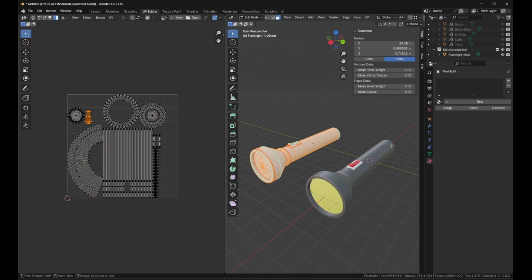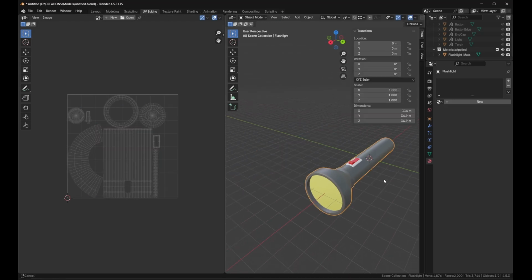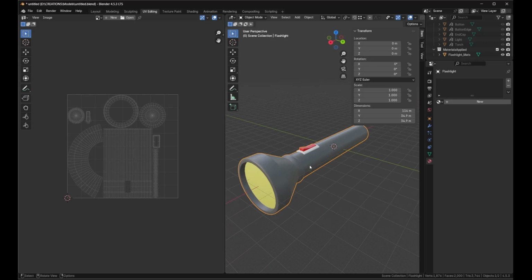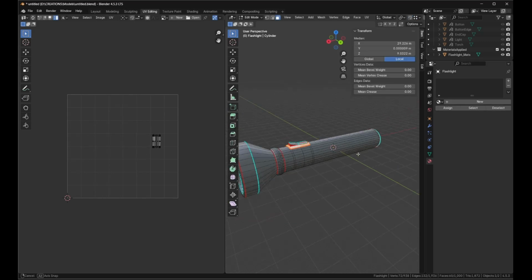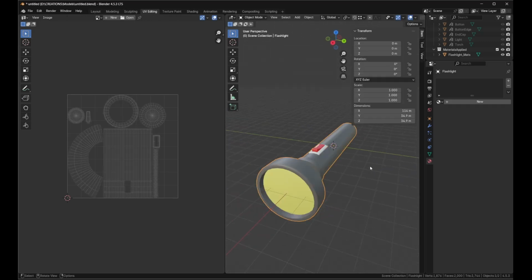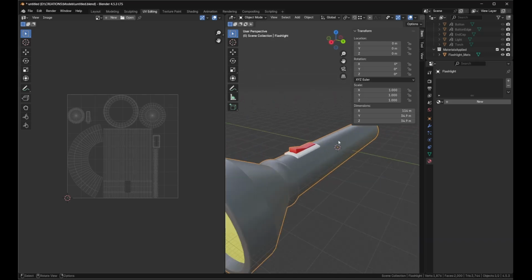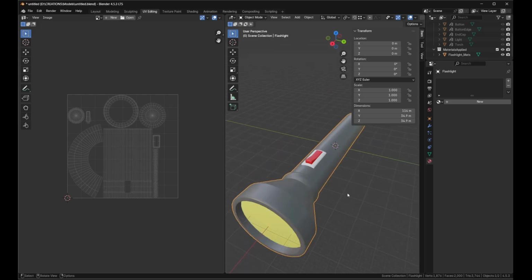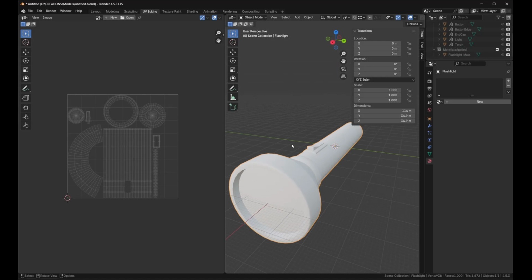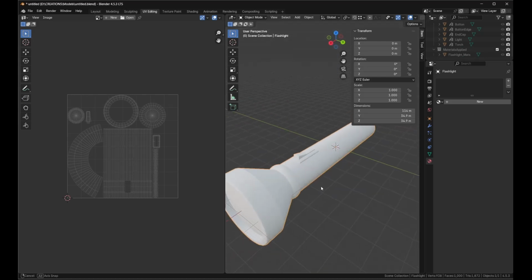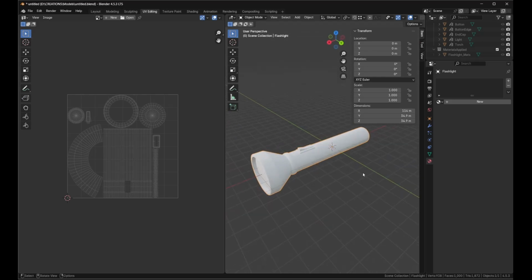But I also have a second identical torch, which I have applied lots of materials to all the different parts of it. And in Substance Painter, you can use a detailed higher poly version of a model to project details onto a lower one. In this case, I'm going to take the material colors from the mesh I don't want to use and use them as a mask to create zones of color on the mesh which only has one material. I'll show you how that works on it.